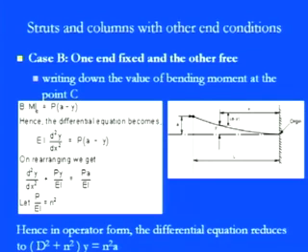When you apply the load, there is a vertical deflection, so we can say that the maximum deflection always comes at the free end. Let us say A is the deflection, and y is the deflection at distance x from the free end. So the bending moment at point C, with the difference of these two, is nothing but P, the applied load, into A minus y. So after applying the basic bending moment equation, we have EI d²y/dx² equals P into (A minus y).